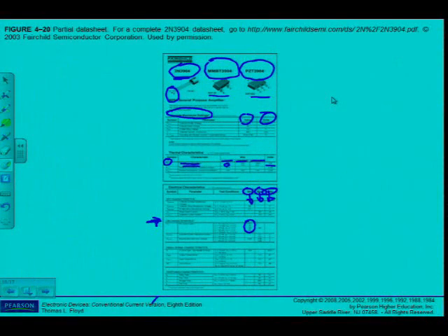Alright, so it's important that you get HFE. And you will see at the end of this chapter some of the problems they ask you in the questions. Do determine this and this and this and use minimum specification or maximum specification. Then I would go and look, what is the minimum HFE in this specific case? And I can see, alright, the smallest number here is 30, for instance. Then I will use that value.